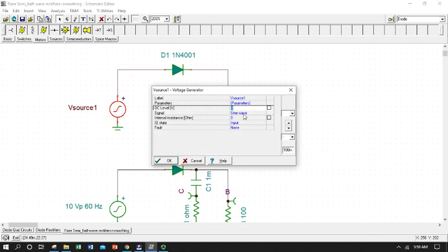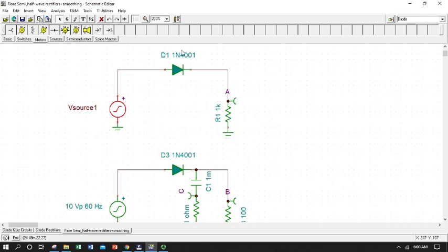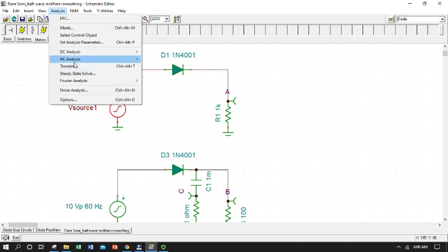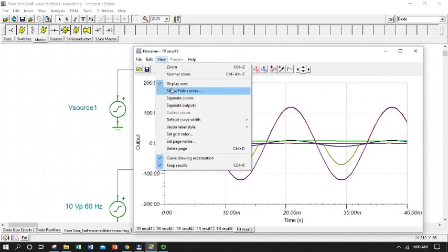What happens if we say, great, I would like this little diode to rectify 120 volts, 60 cycle, coming right out of my wall maybe. So I'm going to try to rectify a typical wall socket grid power output. So I increase the peak voltage of my source up to 120. That's probably a bit higher, or a bit lower, because it's usually 120 RMS. Nonetheless, it's in the ballpark, so I'm going to do that same transient analysis and see what I have.